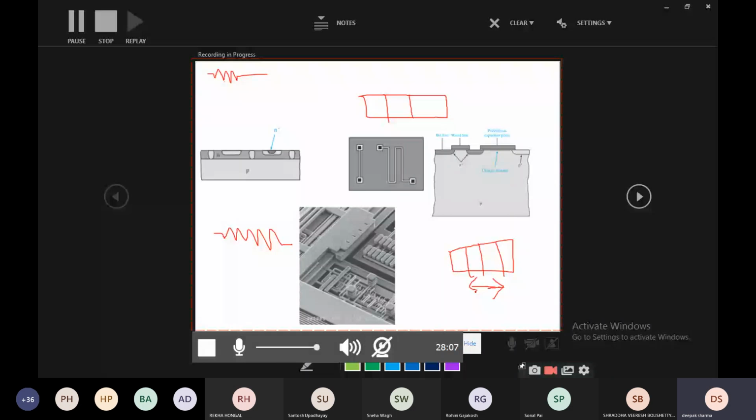Correct. Here also, we can modify this transistor. We can reverse bias it on the junctions where the depletion width can be controlled. So the amount of reverse biasing can control the width of the depletion region, and that width of the depletion region can control the resistivity in turn.